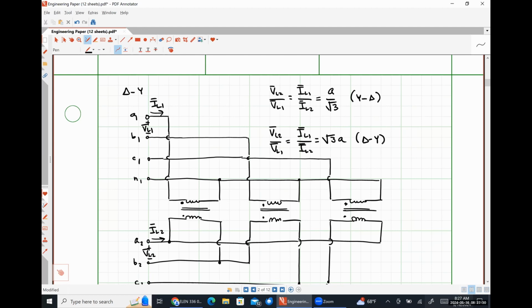So in the time domain, if we had a current flowing down the line in one direction, our return path would be the exact same current flowing down the line in the opposite direction. What you would really see is two sinusoidal currents that are exactly 180 degrees out of phase because they are in opposite directions. They're both sinusoidally varying, but there's a phase difference between them.